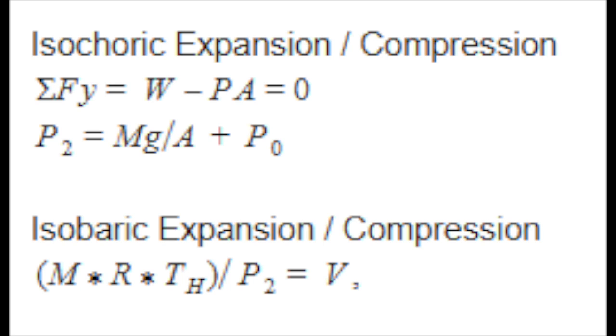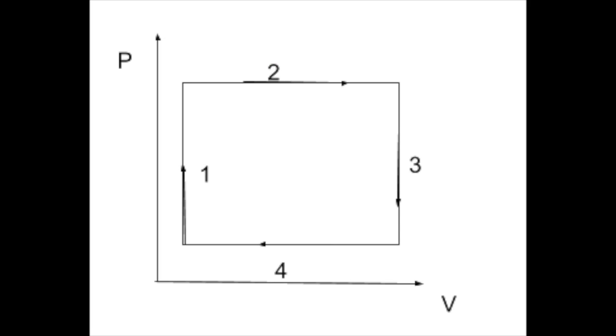The third process would be isochoric compression, since once the piston has reached its greatest volume, the only way that the piston will fall back down is if the pressure changes, which can be induced by changing the temperature of the air. At this state, the metal cylinder will be moved from the hot bath to the cold bath, which will cause the temperature of the system to drop, since heat will move from the hotter object to the cooler object spontaneously. At this part of the cycle, the piston will fall, causing its handle to also fall. However, if we implement the design correctly, the one-way bearing should stop this movement from affecting the storage of the potential energy and keep the rack and the weight at its current height. While the temperature of the air decreases, so does the pressure, since the two properties are directly related.